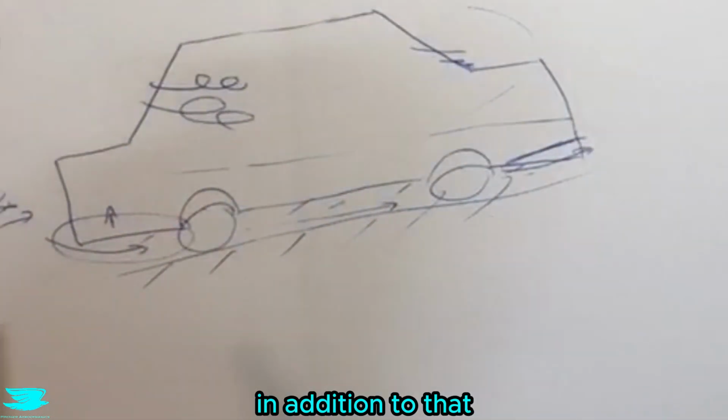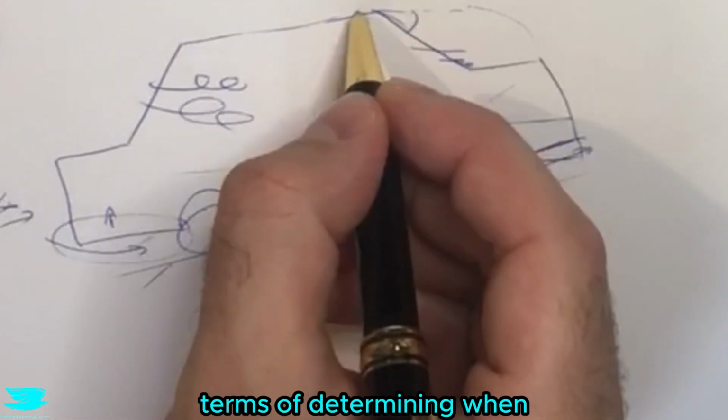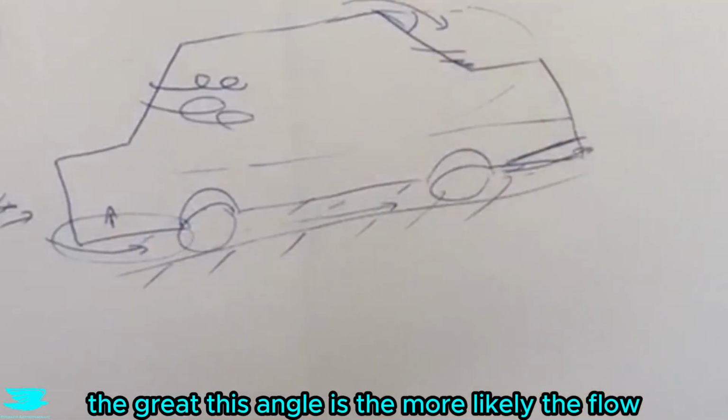In addition to that, we know that this backlight angle here, which we've gone through in this video, is incredibly important in terms of determining when the flow will stay attached and when it won't. The greater this angle is, the more likely the flow won't stay attached.